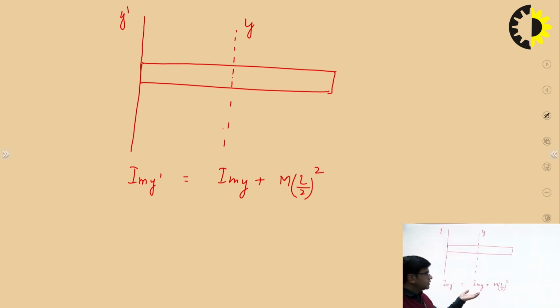Actually, this is based on the concept of the parallel axis theorem, because these two axes are parallel. So, I can get the moment of inertia about this axis after calculating the moment of inertia about this y axis.